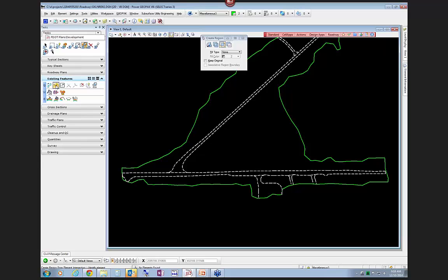And we've gone ahead and added the shortcuts to these tools by just going through this existing features task, and you see this one is actually added to the end here. And then I'm going to choose flood, keep the original. Fill type, I'm going to choose none for now, and then I can narrow or widen this gap for finding elements that are close to one another, so 0.1. And then I'm just going to data point in the middle of the shape, and it will draw a shape when I accept it in this boundary.